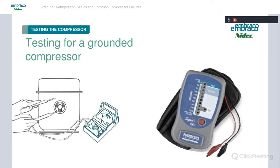If you find this, you're going to want to go ahead and let the customer know that the insulation is breaking down on this compressor, and they could very well have a short, have a compressor go to ground and quit working very soon. It's a good indication that a compressor is getting ready to go out. So very, very good tool to have on your truck, the megohm meter, to test compressors.